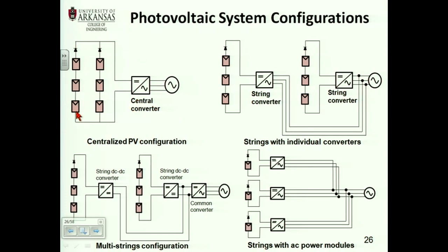And basically that's what I said. To get to the voltage, what you do is you stack them up, the panels, in series. You need a diode so current doesn't flow in the opposite direction. Because what happens if this panel gets shaded, right?